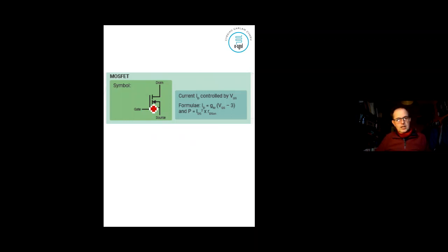All right? They like asking that little question in an exam. So remember your equation basically from the data sheet. You will use that to work out what your drain current is. So yeah, you tend to have a big drain current, but it all depends basically on how much voltage you've got coming in between your gate and your source. So basically your input voltage.